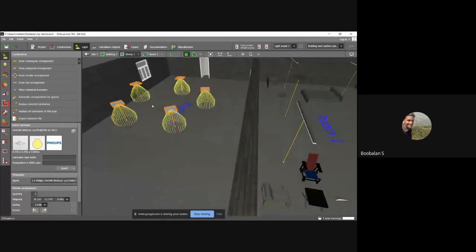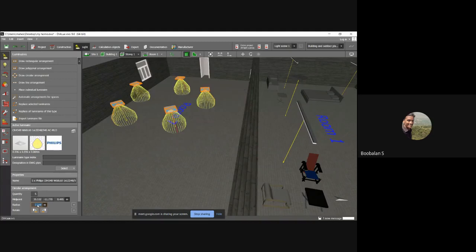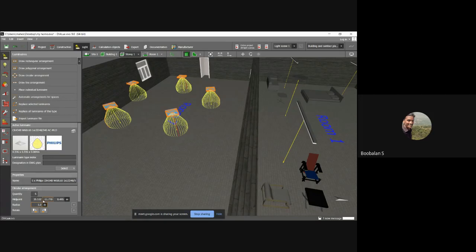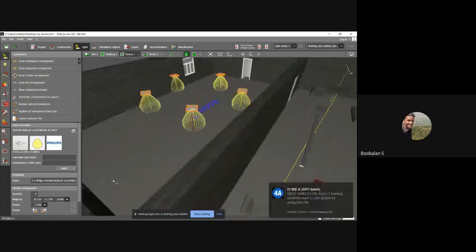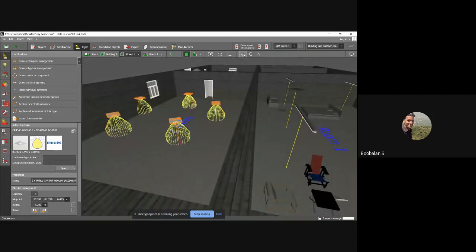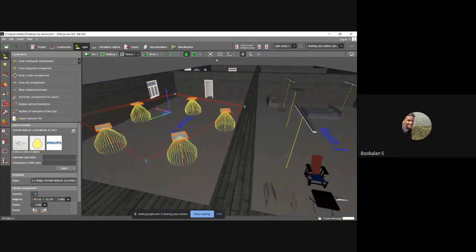You could adjust this position, right? So we could change this radius position, it is 2 meters. So around 5 meters I'm bringing it outside. So the circle radius is now changing into 5 meters. So I'm just going to bring it to 4 meters, maybe 3 meters is more than enough. 3.2. Yes, so you could adjust this position of your lighting system also, right? I'm just going to rotate. The building is at half size, half height. You could change this height also, right? I'm just going to bring it somewhat in a height manner.